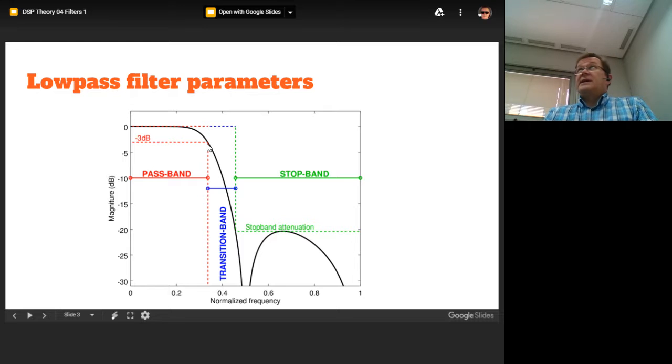On analog filters, it's quite usual that the cutoff is defined at the -3 dB point, but it can also be defined by some other attenuation point. So if we have a filter which has ripple on the passband, usually the level of ripple is actually what defines the cut-off frequency. So just a reminder that it's not always like that.